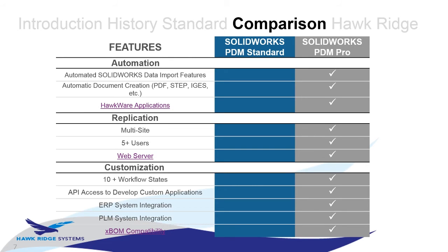And then for other file types, you can see there in the example is STEP and IGES files, but it could be your Parasolids or STLs. So if you do a lot of dumb solids for, let's say, the shop floor, or if you have to outsource it to some manufacturing shop, if they commonly request a Parasolid from you, you can automatically do that same conversion. You can find all of your parts, they get approved, and it'll shoot out that same dumb solid for you to send to them. So a lot of time savings there.